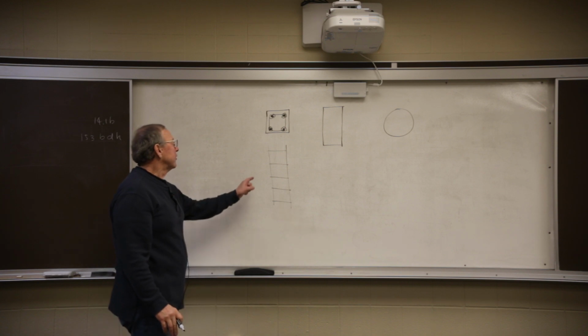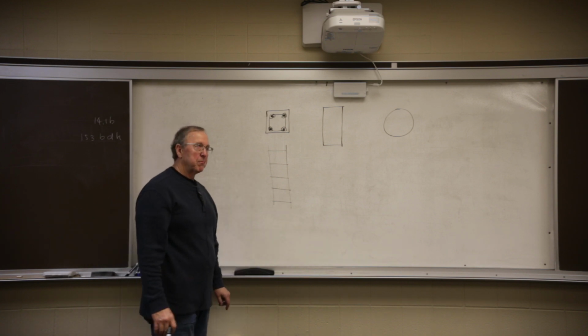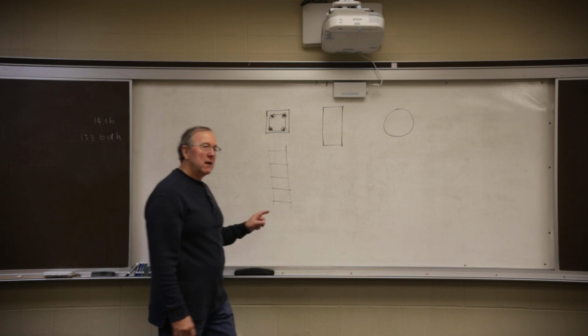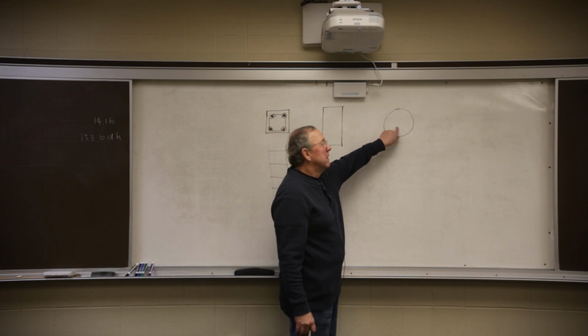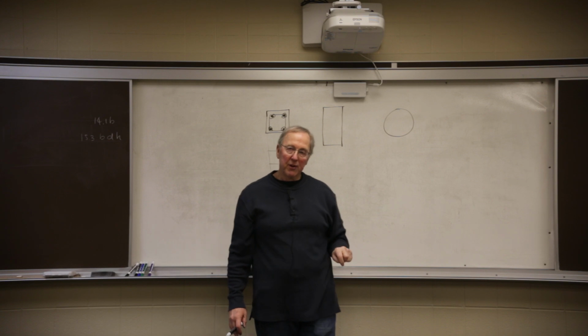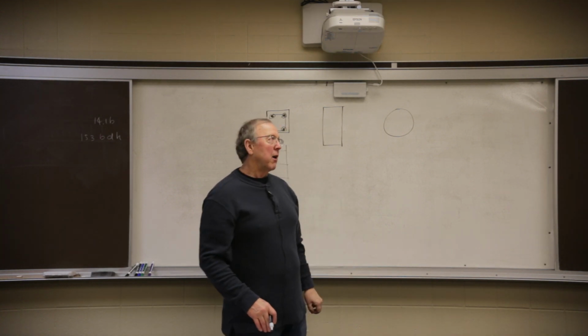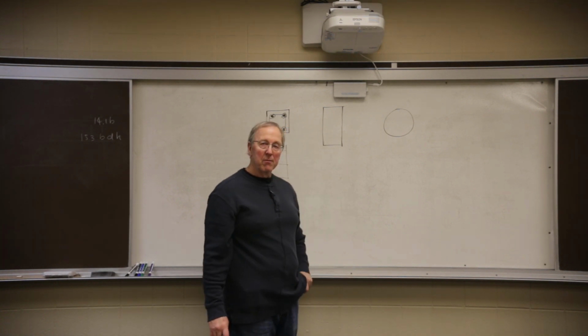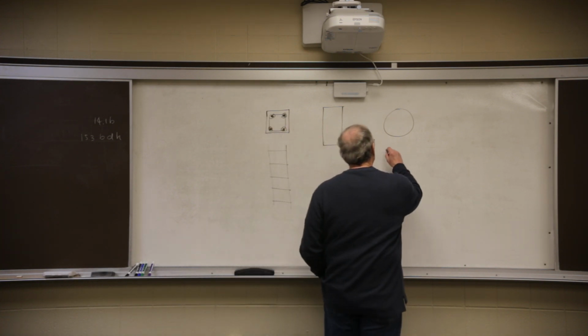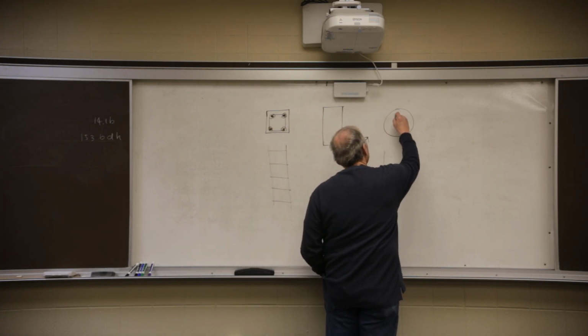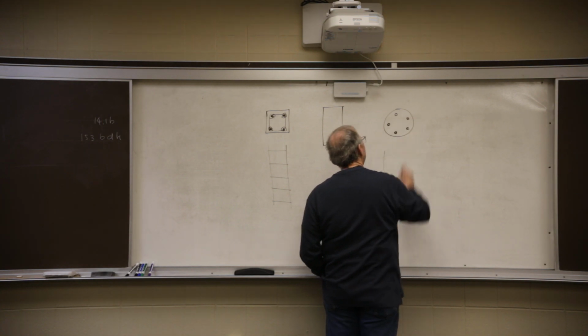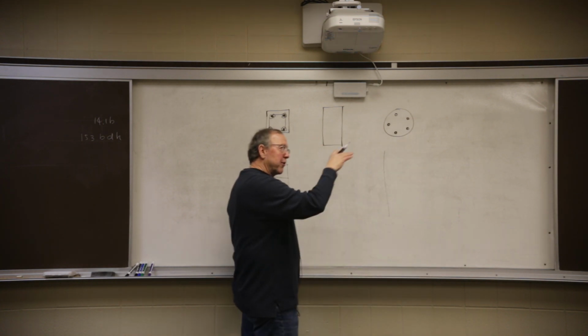So rectangles and squares are basically the same. I have seen square cages dropped into round sonotube forms for round columns. Reason being is that it's cheaper. But the preferred way is to have your bars go around in a circle, and then have a circle go around them.